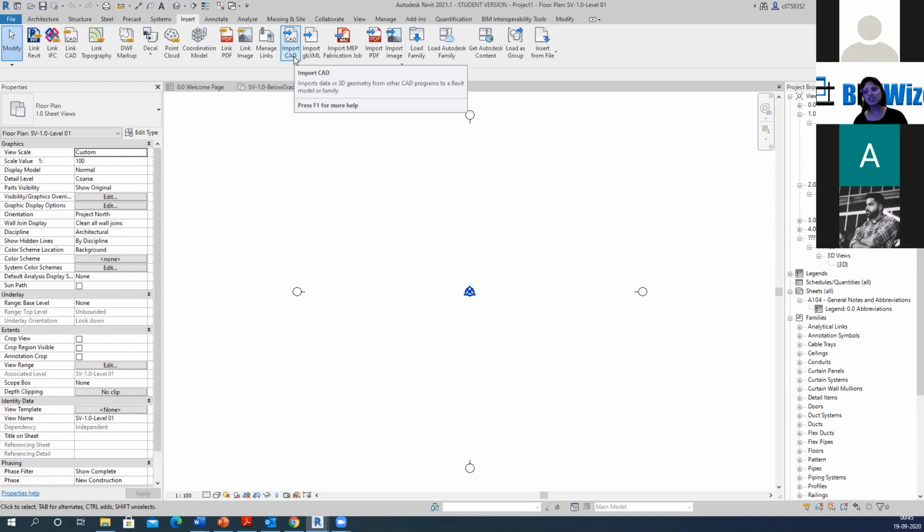While you were making changes, you decided, oh, you know what, this is something I want to quickly show my teacher. So without making changes in your Revit, you just made the changes in CAD and you want to show it to your teacher. The import that you did in your Revit model becomes obsolete. So it's a dead import. Plus, imports also make your model very heavy.